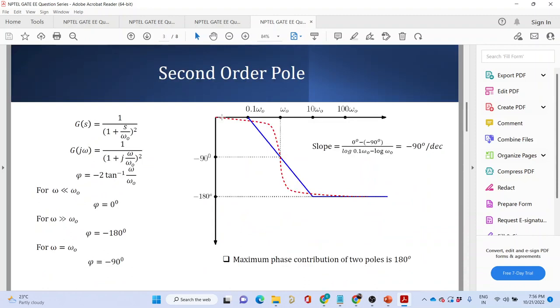So up to omega 0, when frequency is less than the resonant frequency, the phase would be plus 90. It is not drawn over; I'm just telling you how the nature of the plot would look. So it will remain at plus 90. At omega 0, it will suddenly shift to minus 90 and stay like this. Initially it would be capacitive because the current is leading, and then, when you shift a little from this resonant frequency, it will drop down to minus 90 degrees.